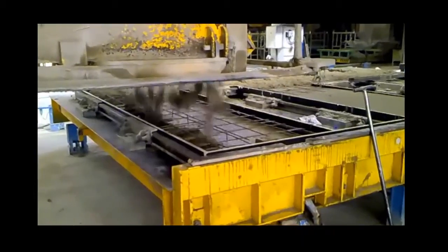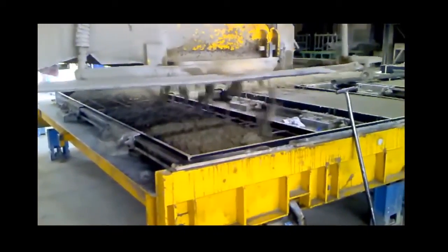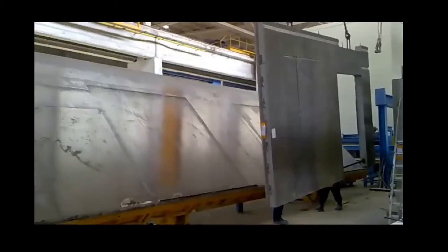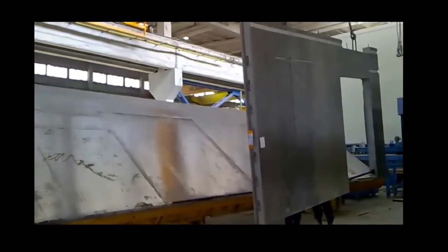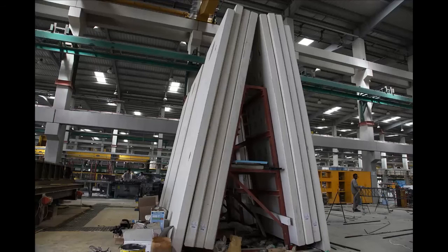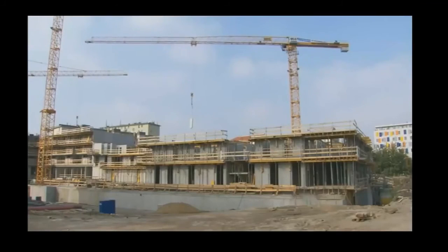The last step is the concrete spreader. This machine fills in the exact amount of concrete which was calculated inside of Revit. After curing, the ready-made wall panel is lifted from the pallet and placed on the transport stack which was defined within the stacker program. After transportation to the site, the panels can be installed.